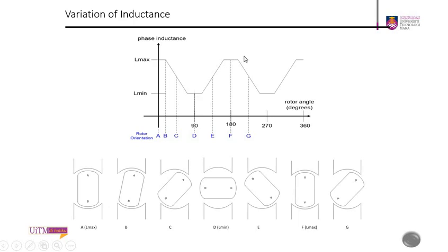As the rotor turns, if you measure the value of phase inductance, you can see a trapezoidal condition here. But this is on simulation; if you measure on an actual motor, the graph will be more sinusoidal.